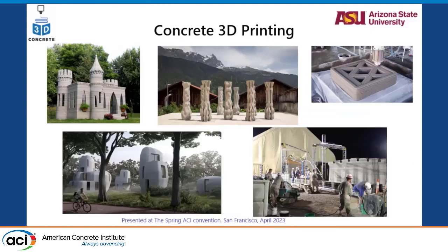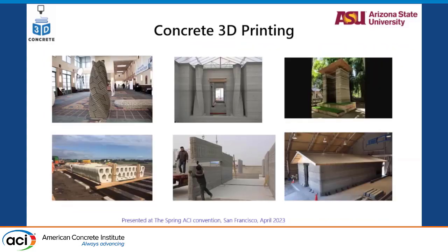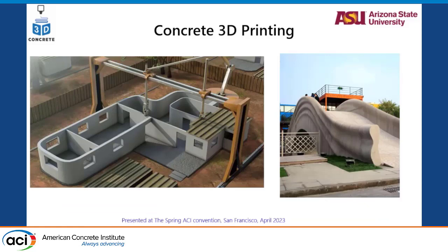Being a 3D session, we have talked about 3D printing a lot. The mode of printing that we at ASU are currently using is layer-wise extrusion. Because you don't have a formwork, you can't keep pouring concrete layer over layer. There's a limit to which you can print, and then after it just breaks down. So proper assessment of buildability is required for us to optimize the printing process and be able to print without failures, without major deterioration.